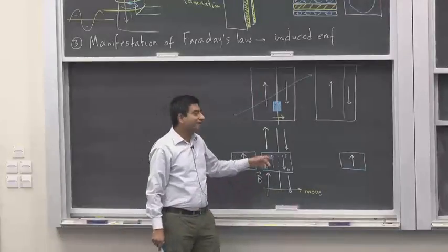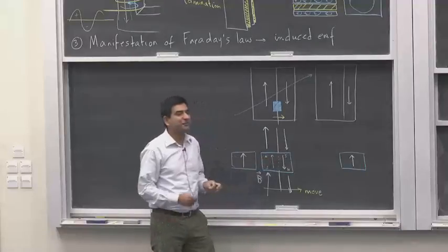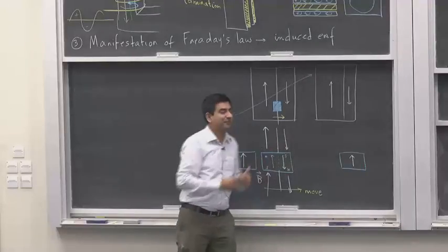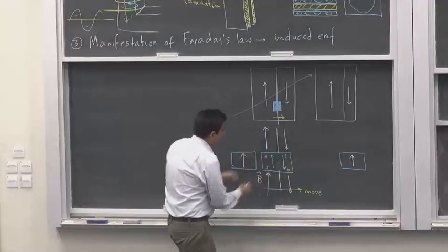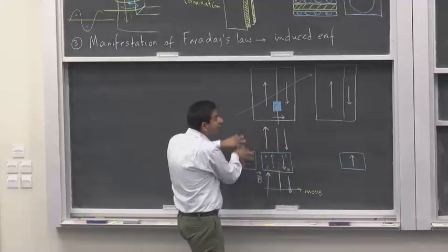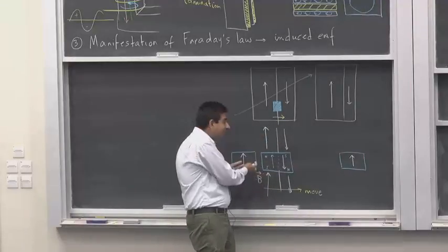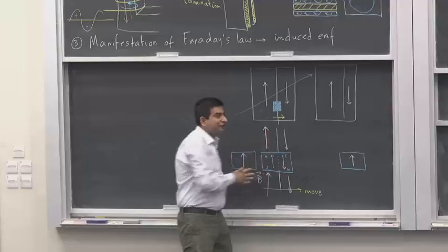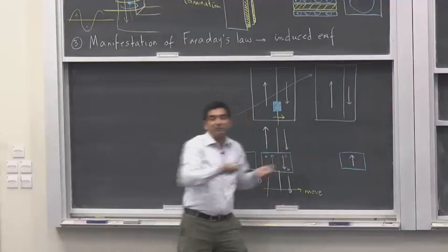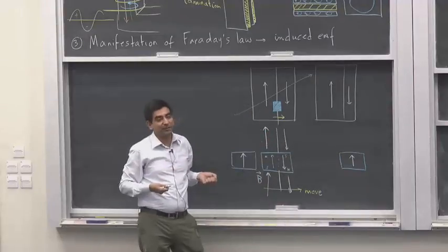So if the domain intercepts an impurity, it would not like to move forward, because if it does move forward, then this impurity will solely and wholly lie within one domain, and it will cause the energy to go up. So the domain wants to move, but the impurities are holding back the domain propagation.